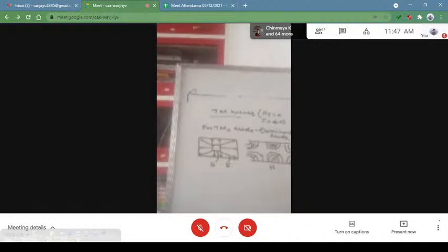Maxwell's curl equations, del cross E and del cross H, are to be used, but the Laplacian operator del squared will be different for the cylindrical, or circular, coordinate system: r, phi, z is used. Again, using the same separation of variables method with product solution and assuming the boundary conditions, we can find the different field components of the waveguide system. Possibly I will take that in the next class, because I would have to write so many equations.